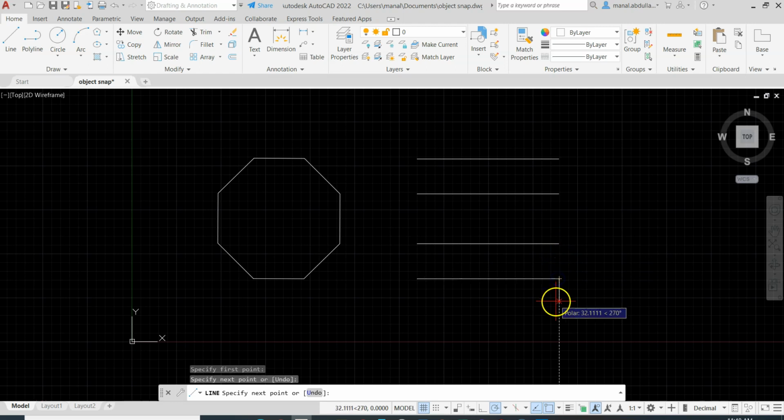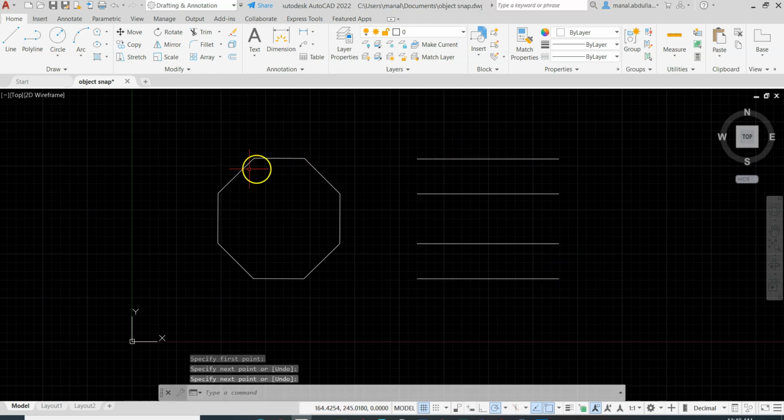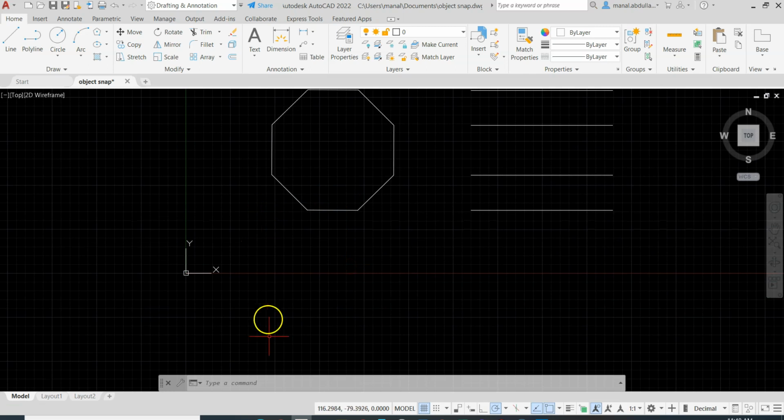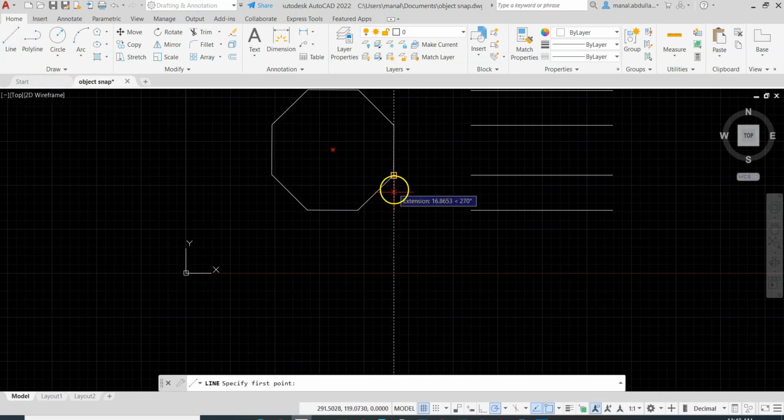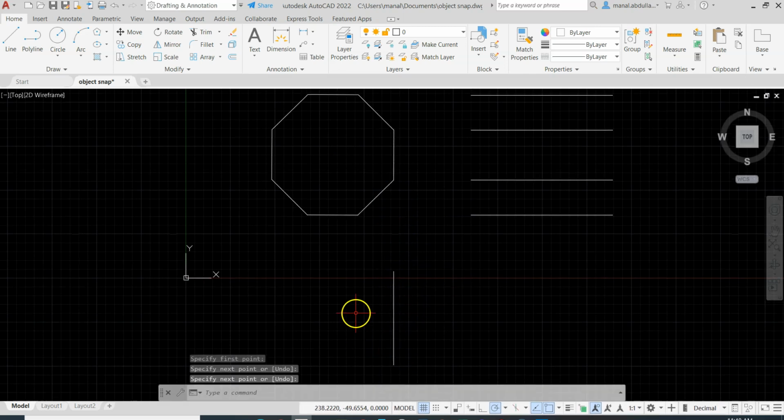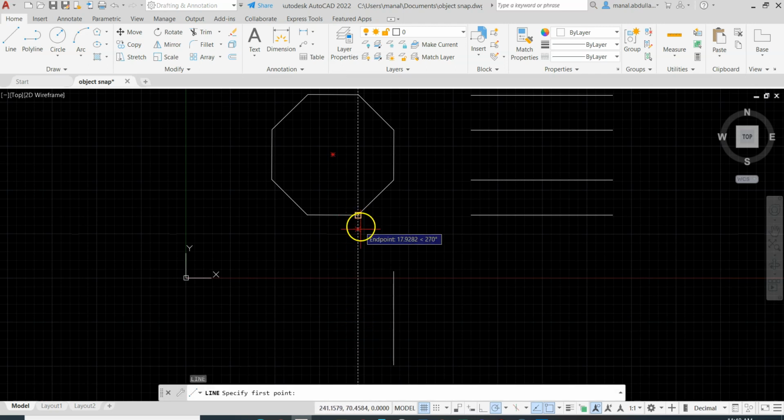Now click. I get all these lines from tracking the point. Now if I'm drawing another elevation down here, I'll do the same thing, line. Let's drag this without clicking, okay? Go down, click anywhere, and draw the line. Hit enter again to repeat the line command.